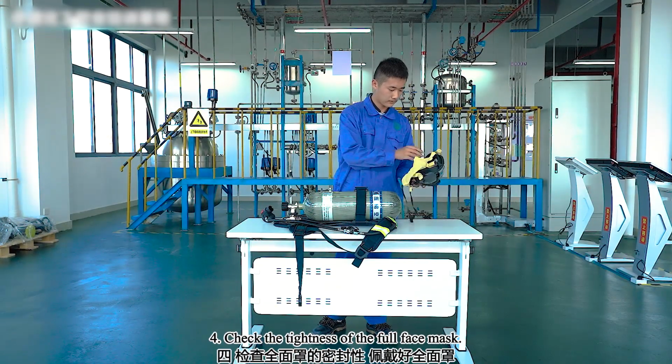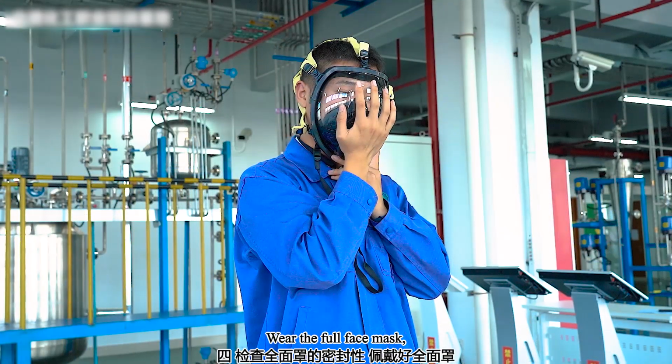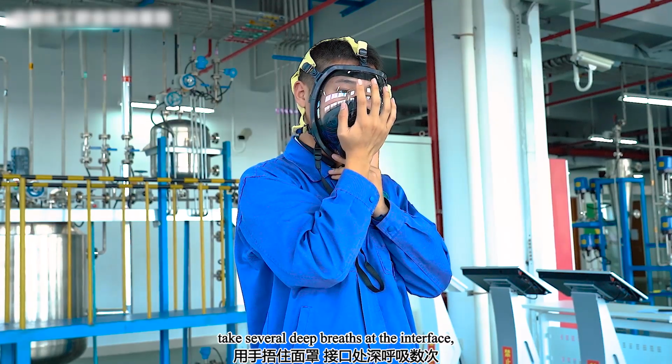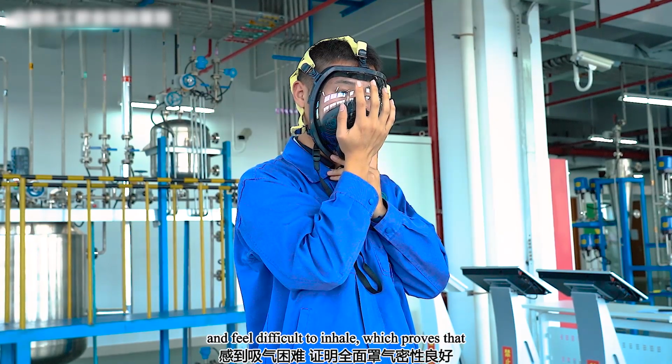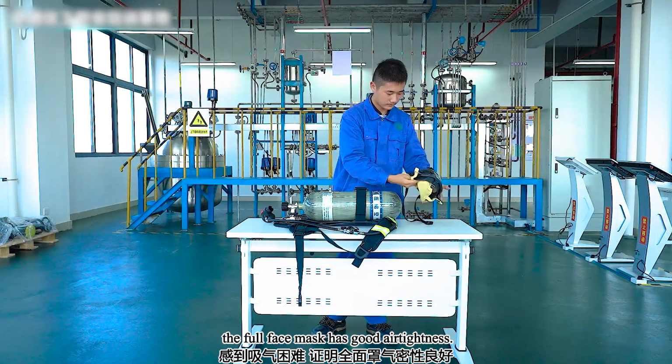Fourth, check the tightness of the full face mask. Wear the full face mask. Cover the mask with your hand, take several deep breaths at the interface, and feel difficult to inhale, which proves that the full face mask has good air tightness.